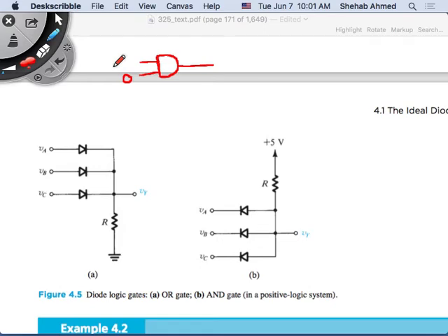It can be 0 and 3.3, 0 and 1.8, 0 and 5, or 1 and 5. It's up to you as a designer. But typically in current digital systems, digital IOs, mainly on processors, would be 0 to 3.3. 0 is for low voltage, and 1 for a high would be about 3.3 volts. So basically, we use zeros and ones only, right?